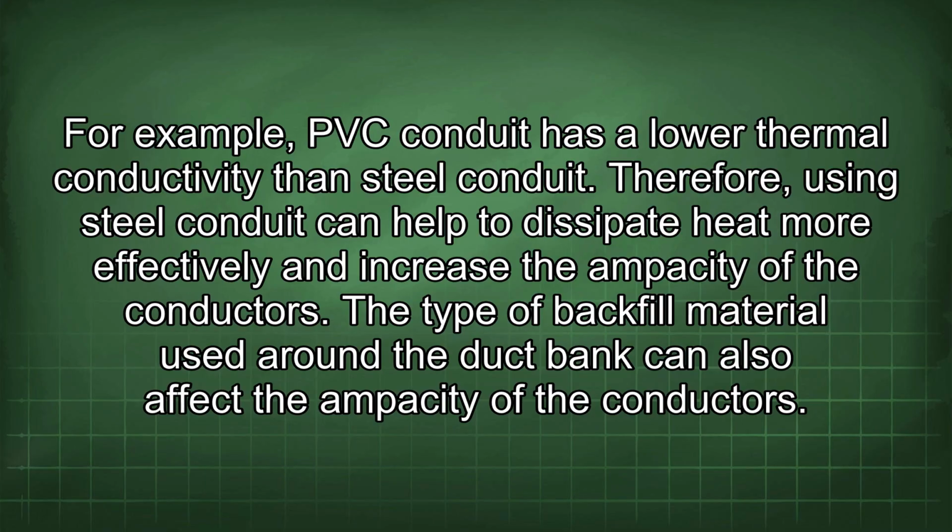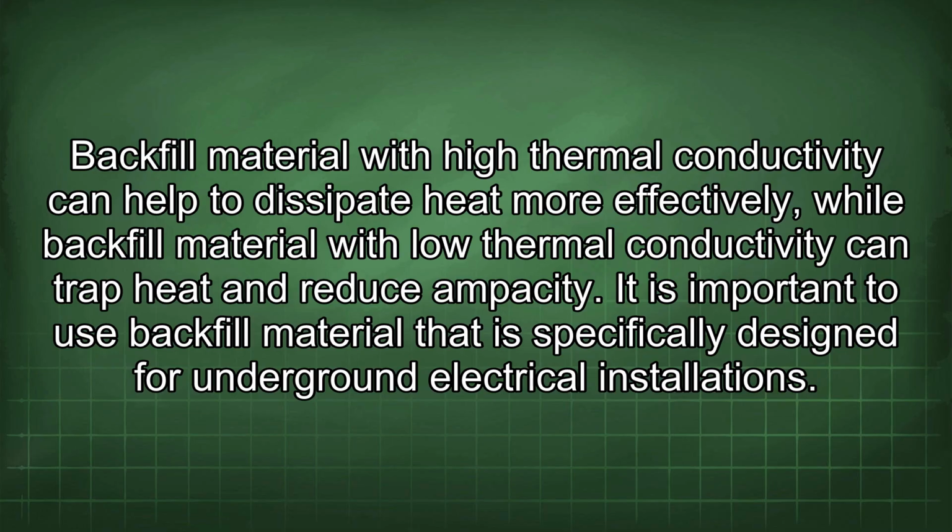The type of backfill material used around the duct bank can also affect the ampacity of the conductors. Backfill material with high thermal conductivity can help to dissipate heat more effectively, while backfill material with low thermal conductivity can trap heat and reduce ampacity. It is important to use backfill material that is specifically designed for underground electrical installations.